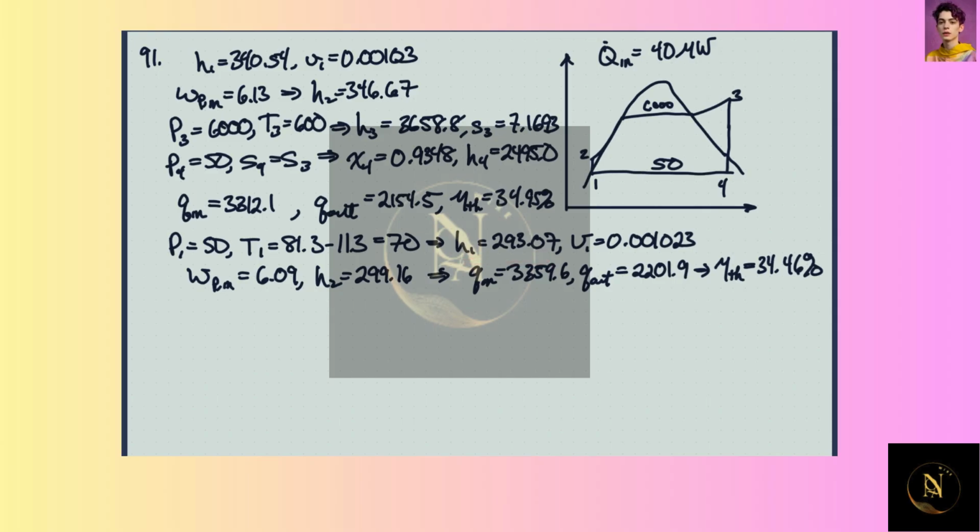And in the end, we wind up with a slightly lower thermal efficiency of about 34.5%. So it's not good to have our feed water supercooled at this point. We'd like it basically just to be on the saturation, have it just be a saturated liquid.